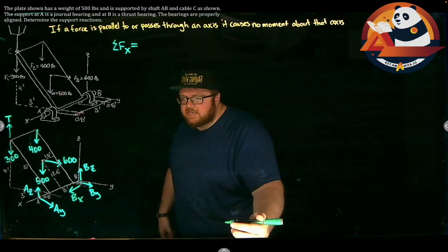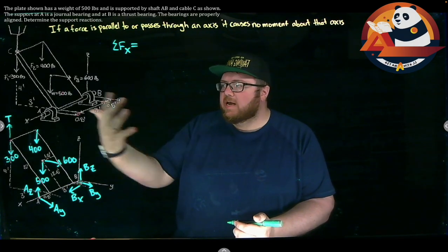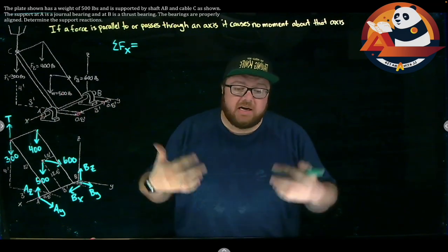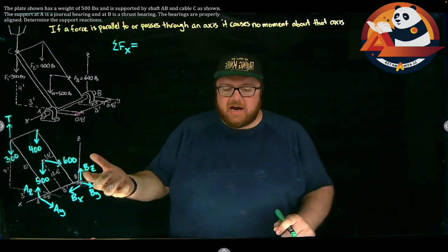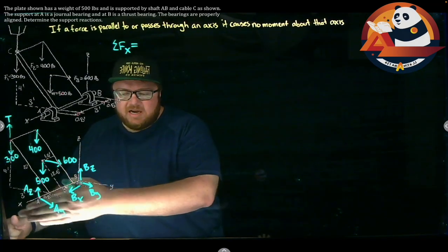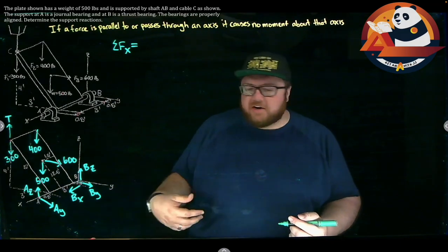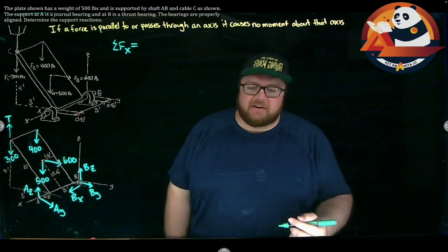For a total of 6 unknowns: AY, AZ, BX, BY, BZ, and our tension T. I have 6 equilibrium equations, so I can tackle these. Also, in 3D, my general approach is to assume everything in the positive direction if I don't have a strong reason to do something different. So that's how we set everything up here.